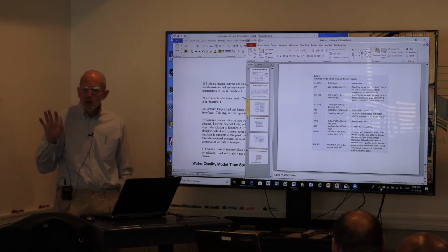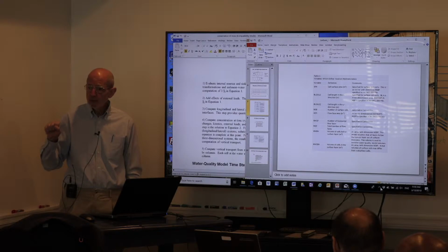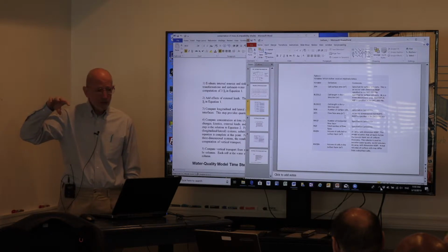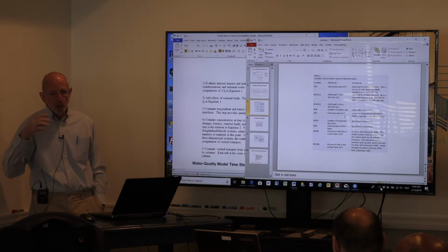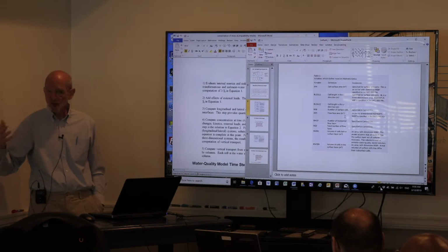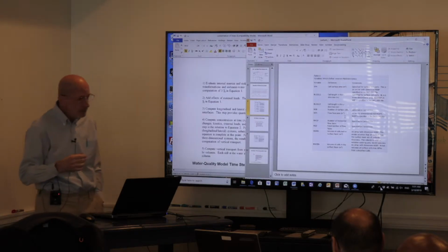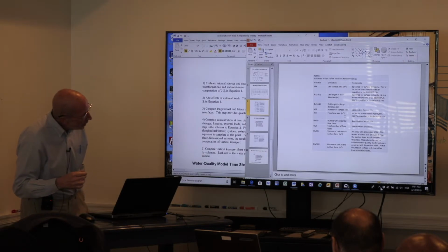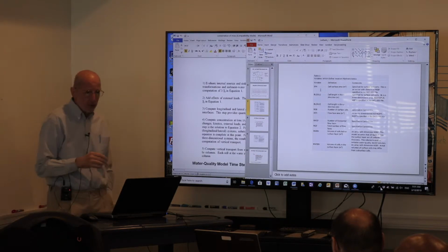Recall that I said that you have to provide information from two places. There's what I'm going to call invariant information that very often will come from a model input file, like what we call a geometry file or a map file. And then there's information that varies, like the flows or the dispersion, that has to come from some hydrodynamic file. So what never varies, I'm going to go over, is the cell surface area.